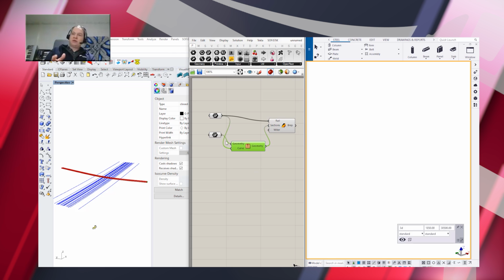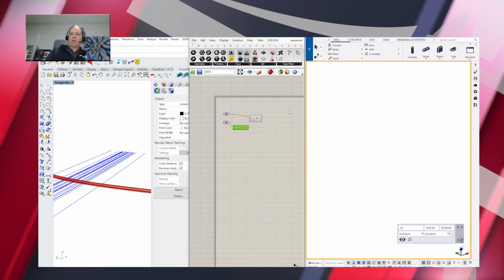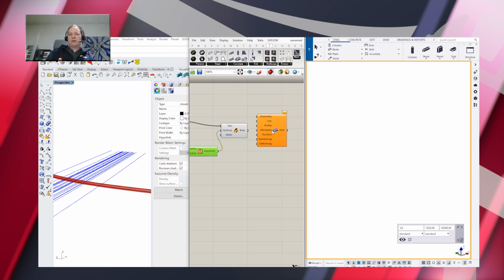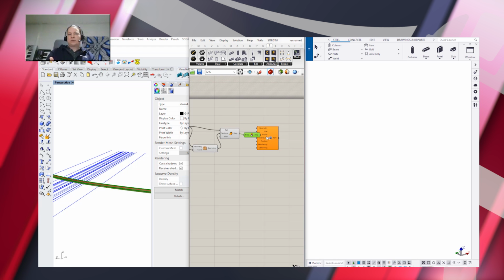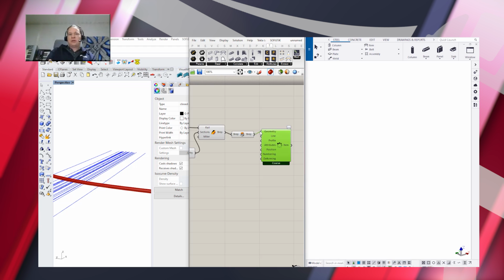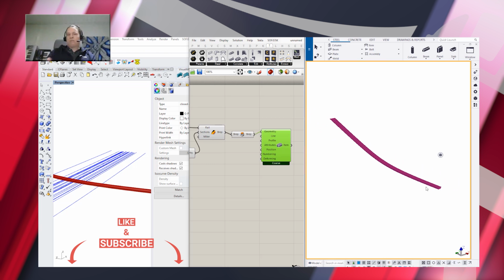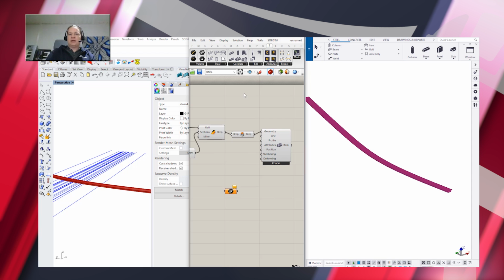And as you saw already on Andres' slides, it's a visual scripting environment. And normally Grasshopper will generate parametric geometry inside of Rhino. So this visual scripting, just to shortly go over that as well, in Grasshopper means that you have your parameters and rules represented by these boxes that we have on screen. And they are also called components. And you can think of these components as functions. So they take some value or maybe geometry as input. They perform a calculation or transformation based on those values. And then they will produce an output result.